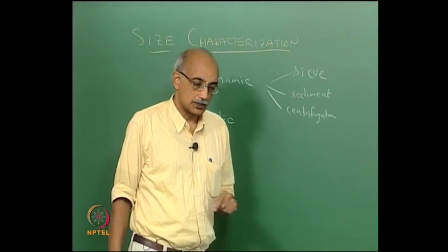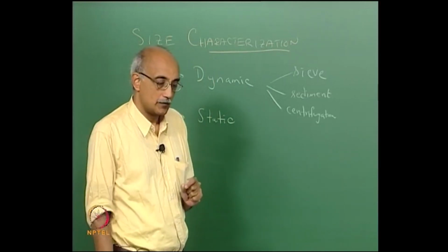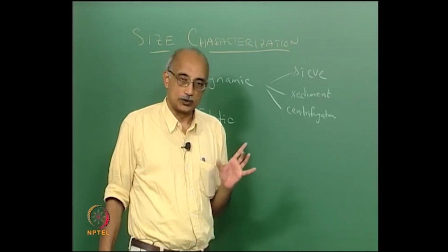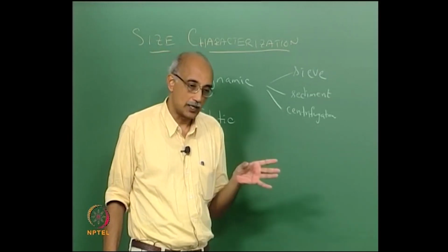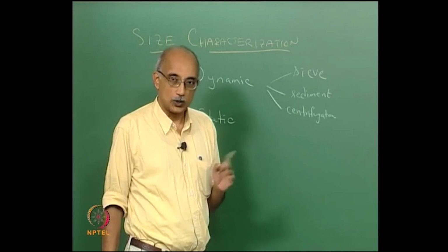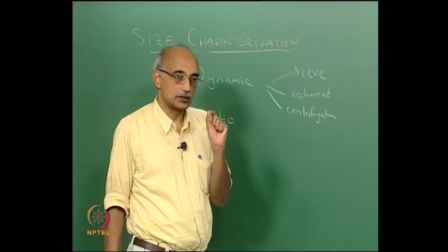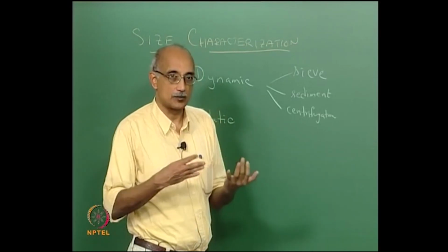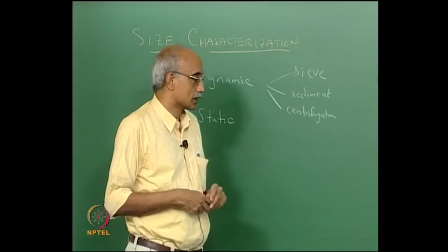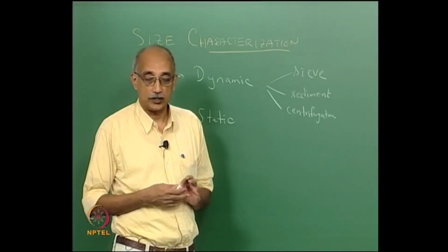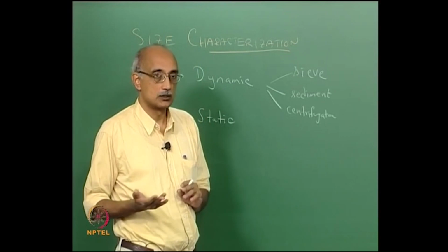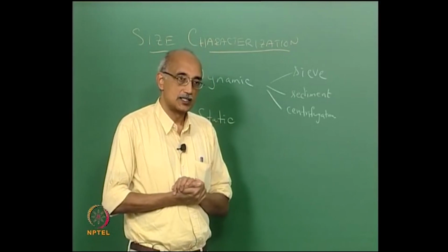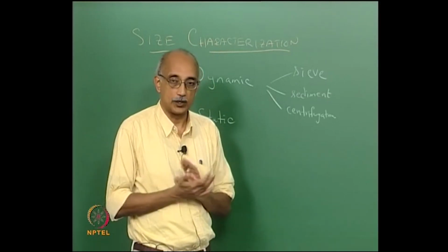Now, in centrifugation also there are limitations which can be overcome in certain ways. For example, a normal centrifuge would probably operate at hundreds of RPM, maybe a few thousands, but if you have very fine particles in the submicron range, for example, the forces will not be sufficient to cause separation of the particles. But there are what are known as ultracentrifuges, where you can actually achieve tens of thousands RPM, and then these forces are large enough to be able to separate even very fine particles.